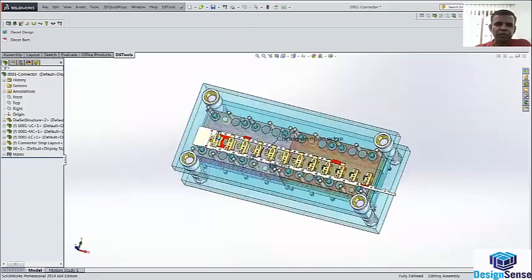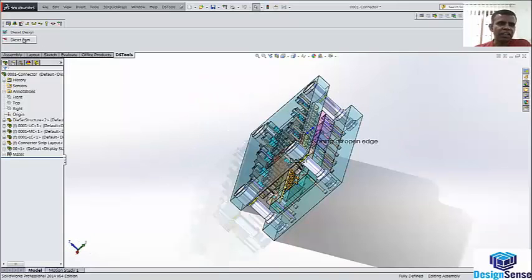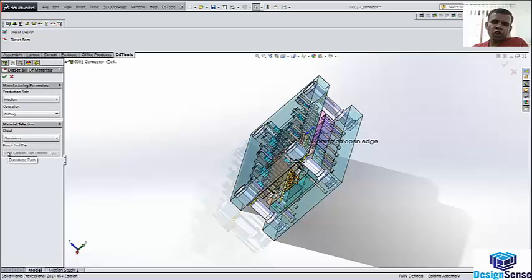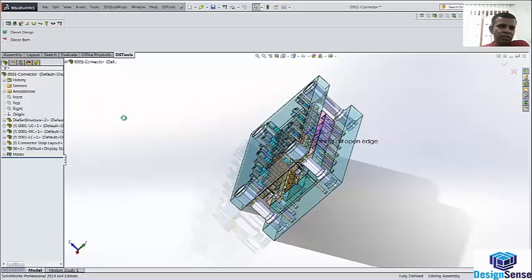Now that we have come up to this point, let me show you our die set BOM. The choice of the materials is decided based on what the production rate is, what kind of operation we are looking at, and what the raw material is. Now I'm choosing a very high production rate, and the raw material being used for manufacturing this particular part is brass. So we are choosing the materials and attaching the right materials to the different parts.